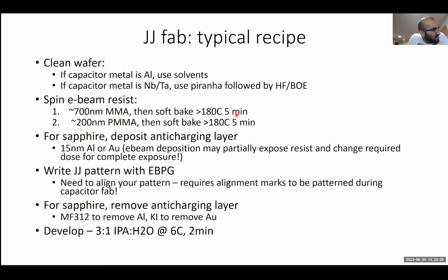So I'll answer that second question first. When your junction ages, your resistance will usually increase, which means your LJ will decrease, which means your frequency will decrease, which means that for a fixed internal Q, your T1 will increase, right?